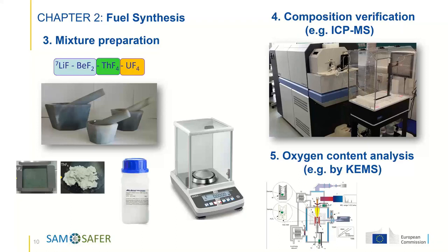The only thing is, again, I put the accent that all open handling of salts, even at room temperature, we handle in argon glove boxes, which are connected to purifiers and constantly monitored for oxygen and water impurities, and they must be really in detail. That also applies to non-radioactive materials, because the molten salts in general all behave like that. Some more, some less, but the protection should be in place.